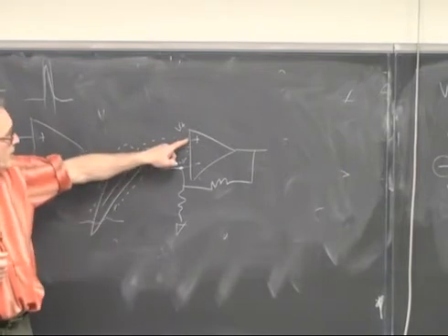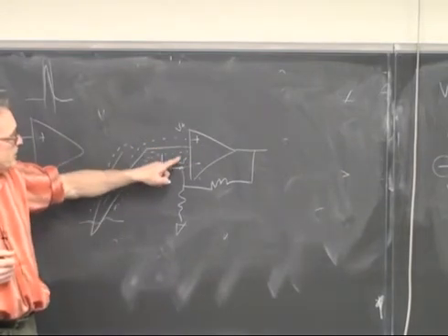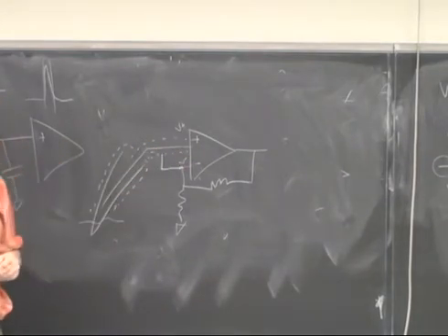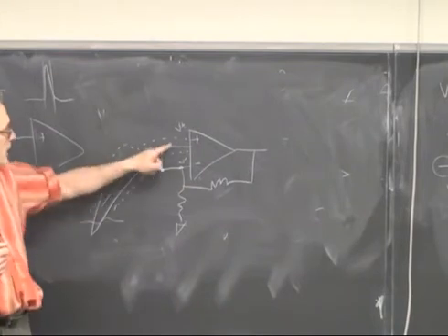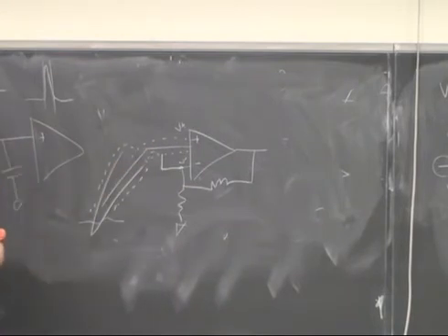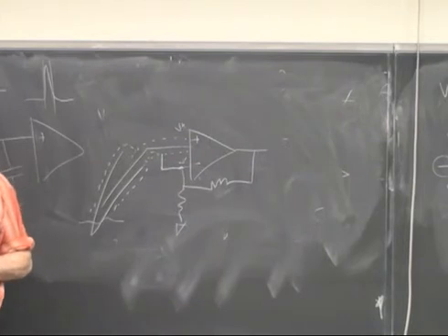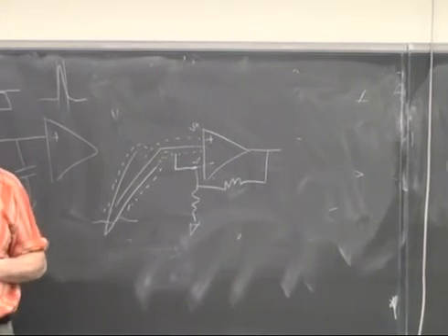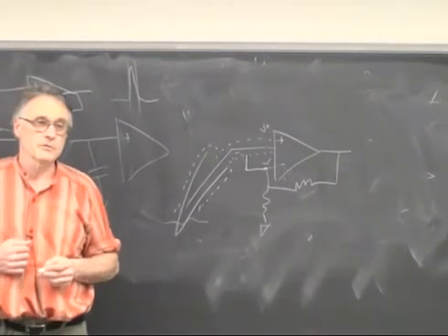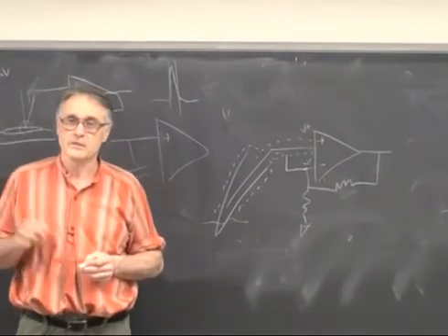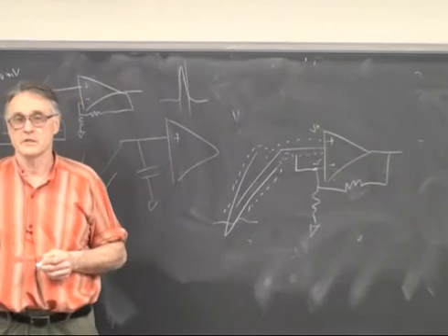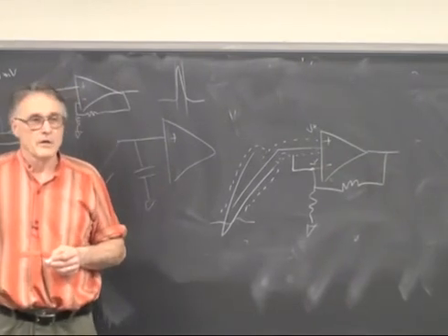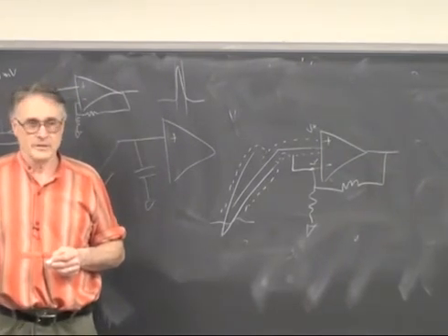Now, if we hold the voltage on the shield exactly equal to the voltage on the center conductor, whatever capacitance is there can't charge, right? You're locking the charge accumulation at 0 because the voltage difference is 0, and so you've nullified the capacitance.